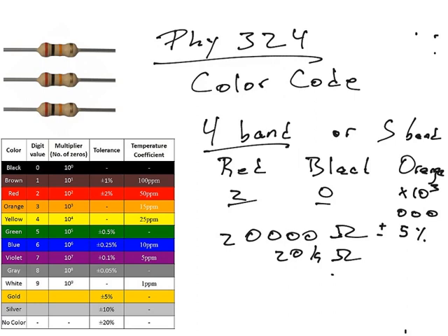Very, very easy. Of course, young people have it a little easier than us old people, being able to see the colors on these resistors, because resistors are fairly small. In fact, this picture is a little bit zoomed in. An actual resistor is smaller than that. So it's not always very easy to see which exact colors these are. Like, is that an orange, or is that a yellow, or is that a brown? But eventually you get used to it. If you can see the colors, then you just use this little chart, and that'll tell you what the resistance of the particular resistor is.